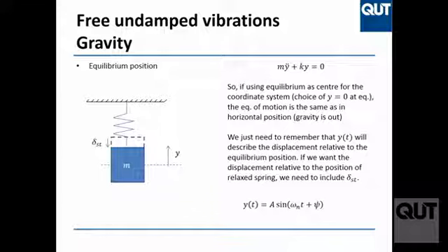So the idea of a vibration problem is this one. Start with the free body diagram, write Newton's law, then play with the equation to obtain an equation which always looks like this. Once it looks like this, you know the solution is that one. You solve your differential equation without solving it, because you know the solution is that one. Okay? Clear?